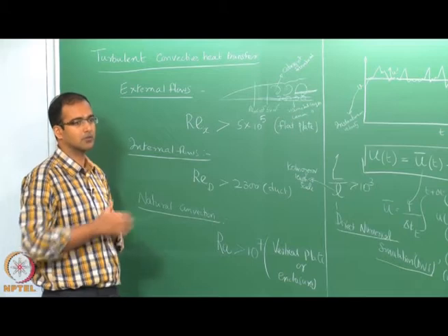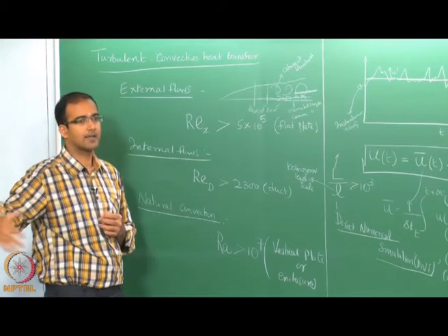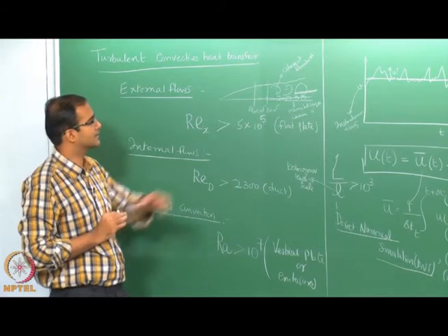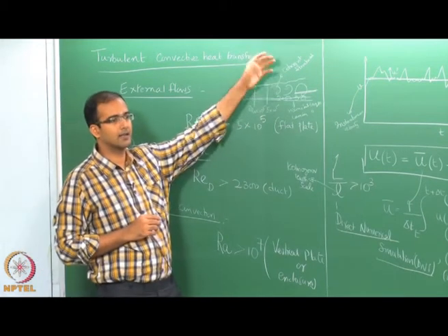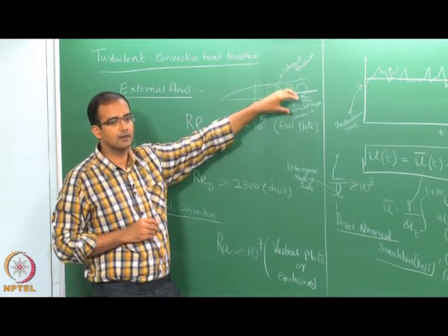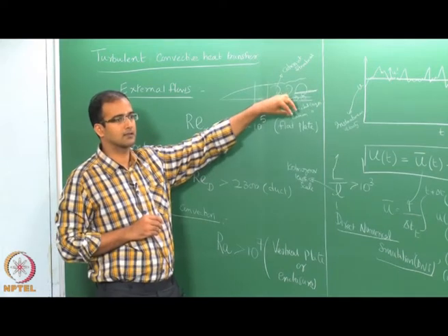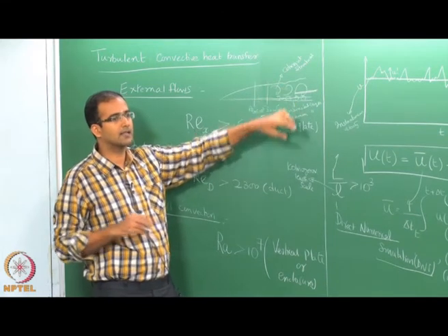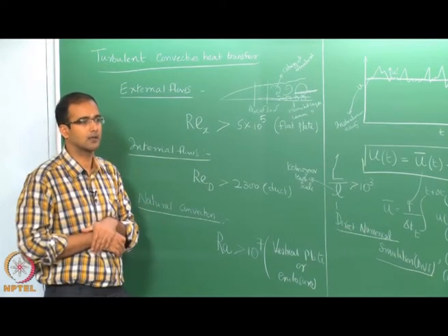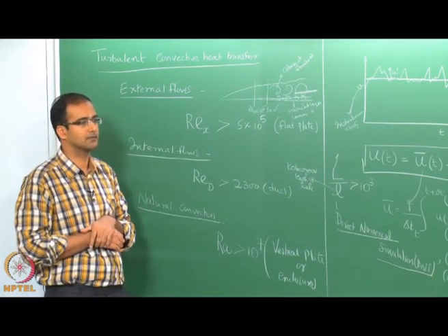So, you will be able to show an energy cascade. Okay. So, that shows that the turbulent kinetic energy is transferred from the largest scales finally to the Kolmogorov scales. Okay. And finally, that energy is dissipated as heat at the wall due to the viscous dissipation.